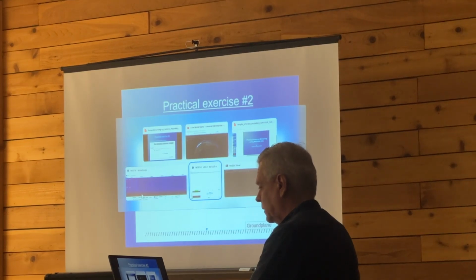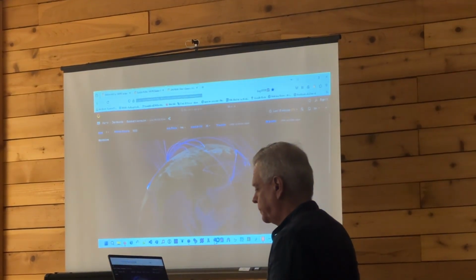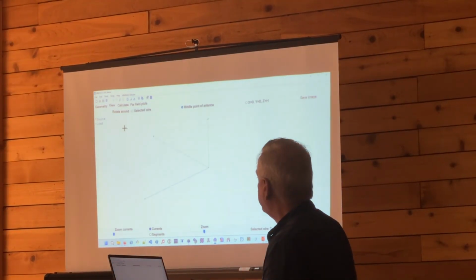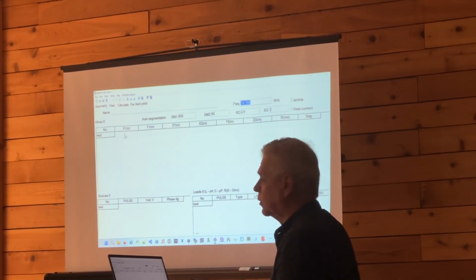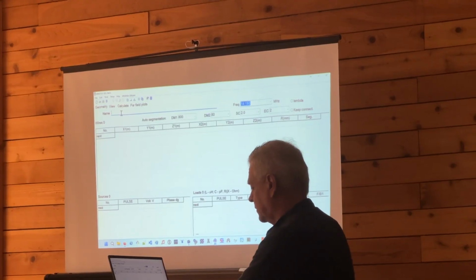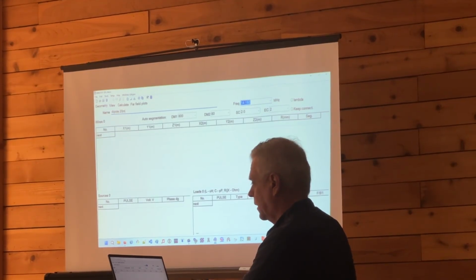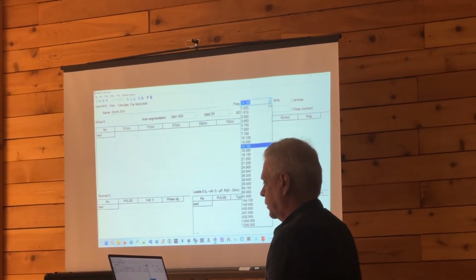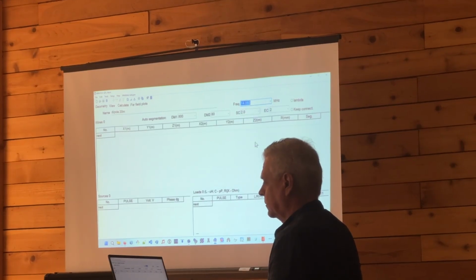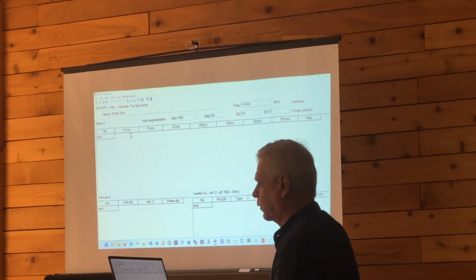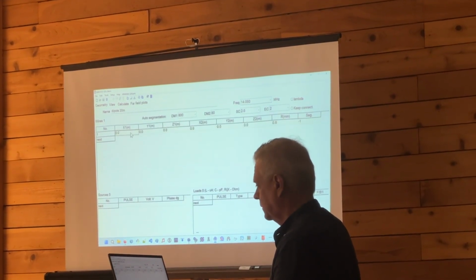We go over here, and we click on MMANA GAL, and the program launches. The program, by the way, is launching in the View tab. We click over here on Geometry, and we're back to our old friend. We'll put in our name. This is going to be dipole, 20 meters. And we're going to again put in here, out of all of these, the 14.05, the CW portion. And here, as before, we click on the X1 cell, hit enter.